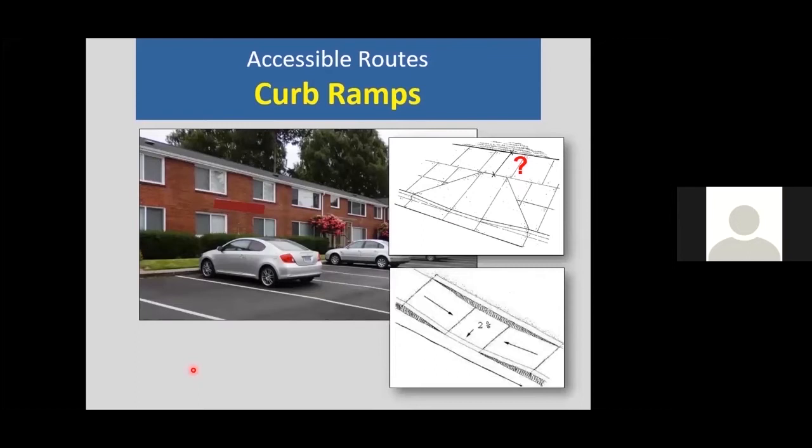And here's just another illustration of curb ramps. This is the problem that we often see. This may not have been designed to be wide enough. And so we might end up having this portion, which is required to be compliant, actually existing along this portion, and the flares will make the slopes non-compliant.